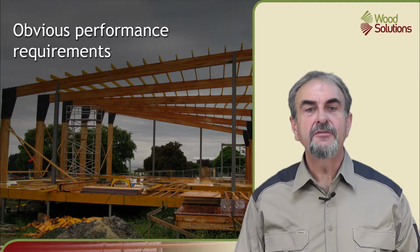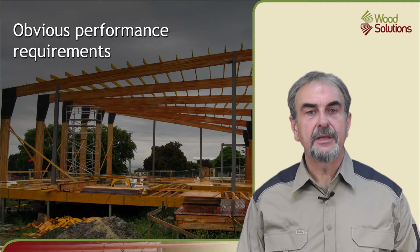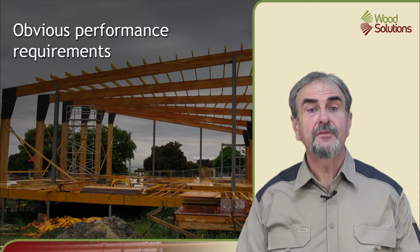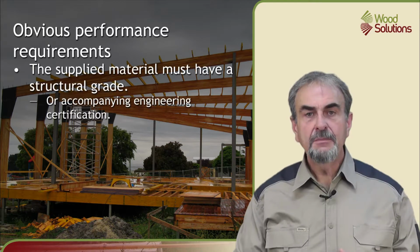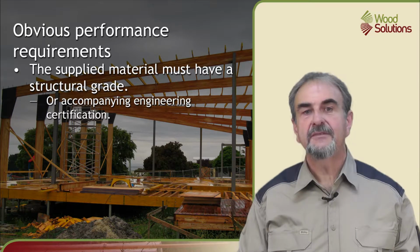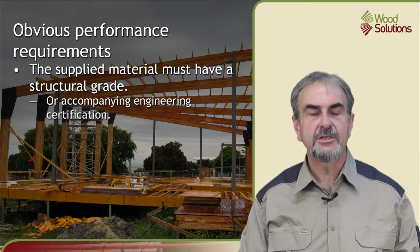Regulatory compliance is the overriding fit-for-purpose consideration with structural material. All structural applications are regulated, and any timber or wood product used in them needs to provide the structural performance required by the structural design standards called up in the regulations. To provide this structural performance, they have to be of a specific size and grade, so the obvious performance requirements are that the supplied material must have a structural grade or accompanying engineering certification. If it does not have a structural grade or certification, it is not fit for use in structural application.